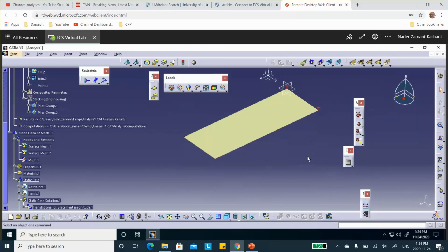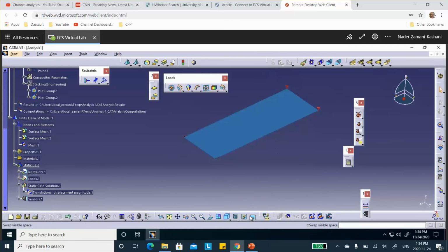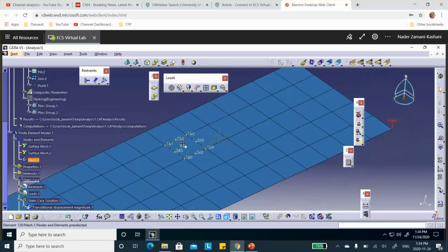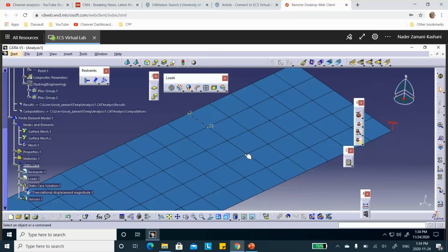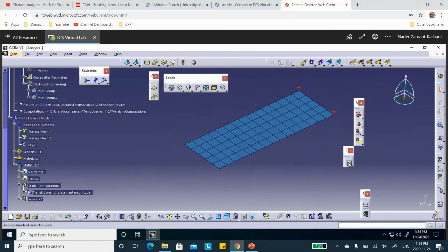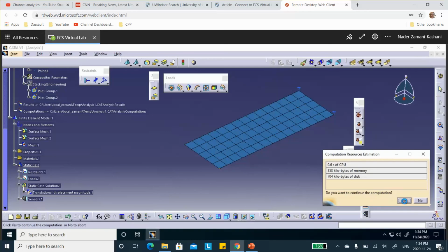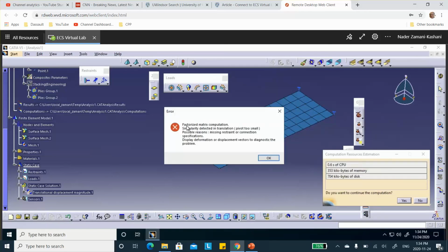Now, if you say show me the mesh, right click mesh visualization, change the rendering to this. The separation line that I had was here. Look, when you put the cursor on this side, this node 27 is on that line. When you go to the other side, the node is 156. These are separate nodes. This is why when I try to run this thing, it will bomb out. It will not finish. See, it says singularity detected, basically cannot solve the problem.